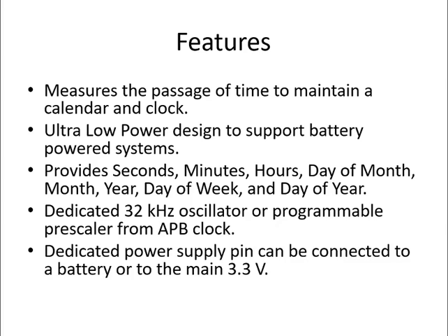Today we are going to see the real-time clock, RTC. RTC basically measures the passage of time to maintain a calendar and clock. It will measure the time in terms of seconds, minutes and hours. In the LPC 2148, we have an ultra low power design to support battery powered systems. It works on a 3.3 volt battery.